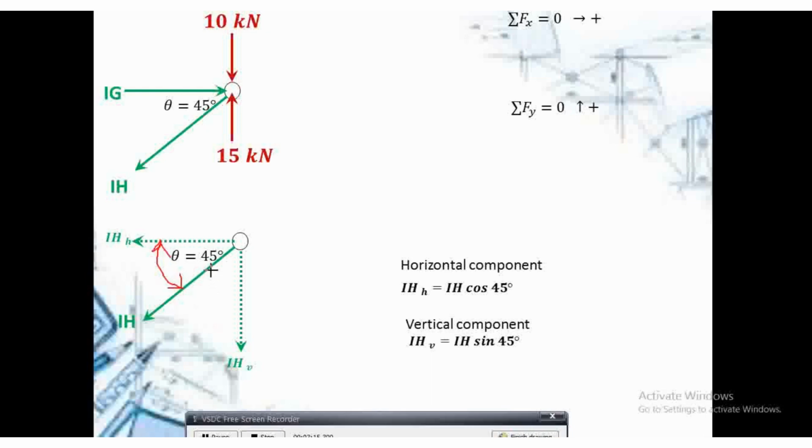So, let's say the given angle is this. When the angle is here, the easiest way so that you don't get confused is, let's say the given is beta, to determine the horizontal and vertical component, take whatever angle is here. Because our basis is always the horizon. Okay? When we say horizontal component, force multiplied by the cosine of the angle. Vertical component, force multiplied by the sine of the angle.